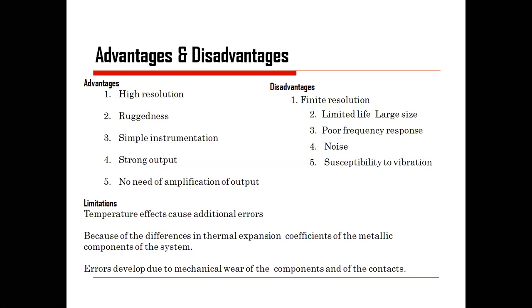Also, the significant thing is that there is no need to design any signal conditioning device to amplify the signal. As we will see in temperature measurement, the resultant output of a thermocouple is in millivolts, which is not of use, so we have to amplify that. But here, in the primary and secondary system we have studied, there is no need to amplify the signal, so the design cost and complexity have been reduced.